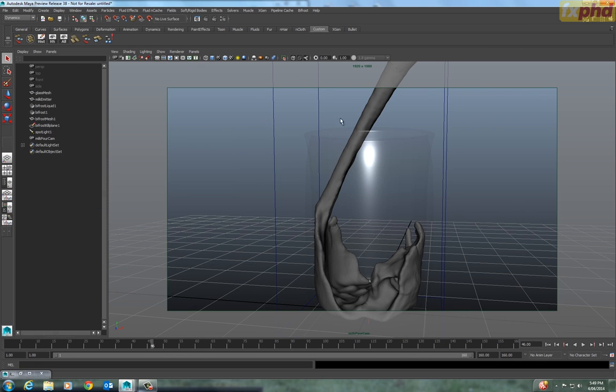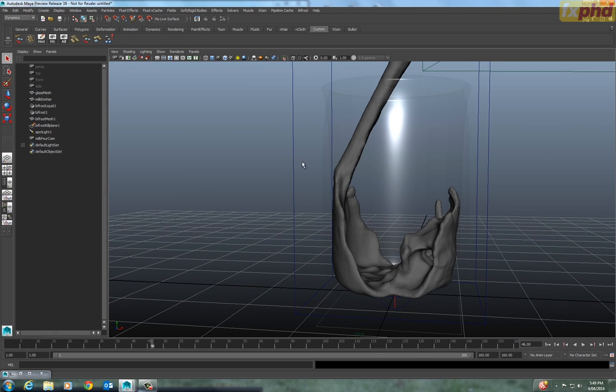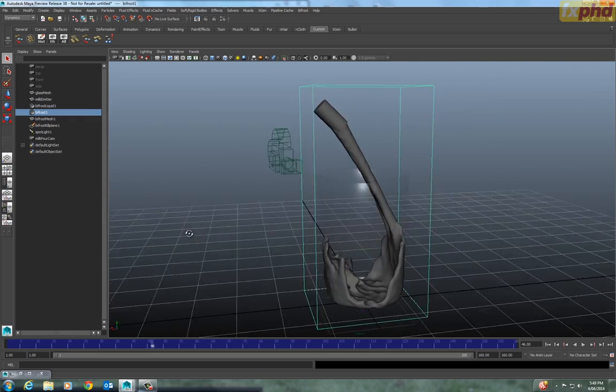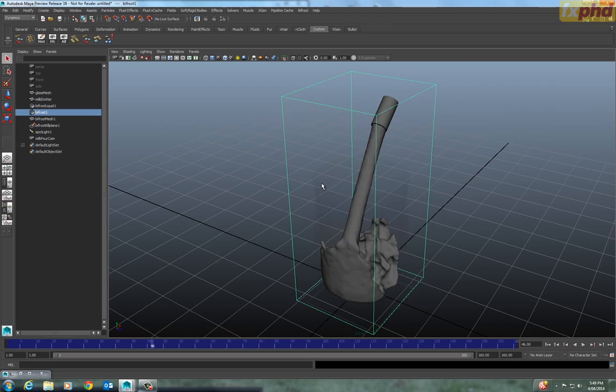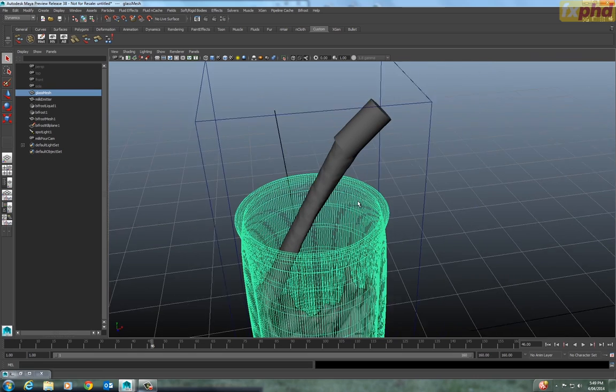I've just meshed this in the viewport so you can see where the actual liquid is pouring. So the cylinder at the top is the fluid emitter, and this glass shape here is a collider. So that's what the fluid's emitting from.